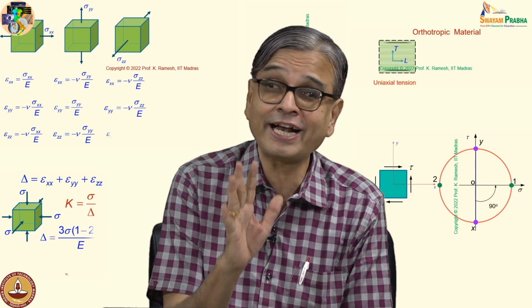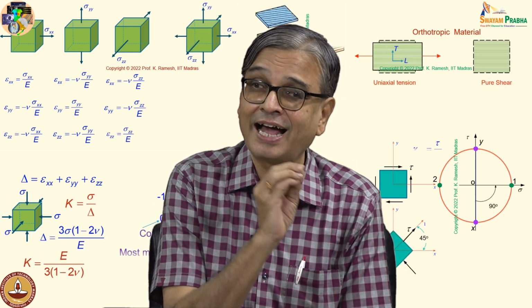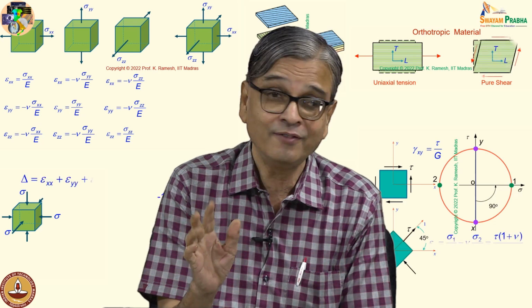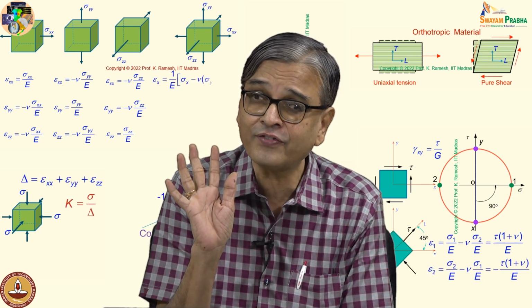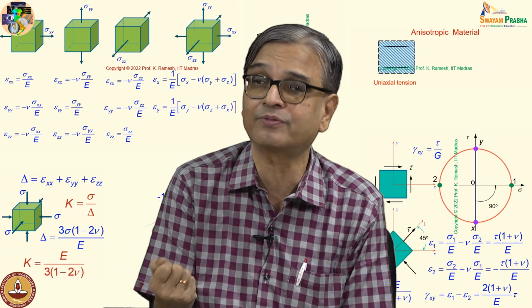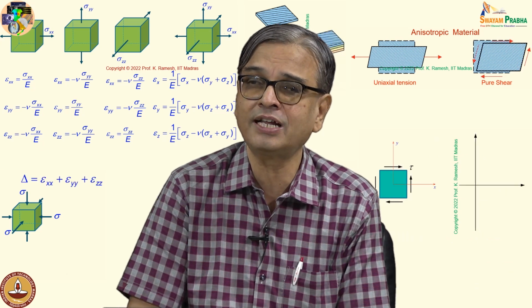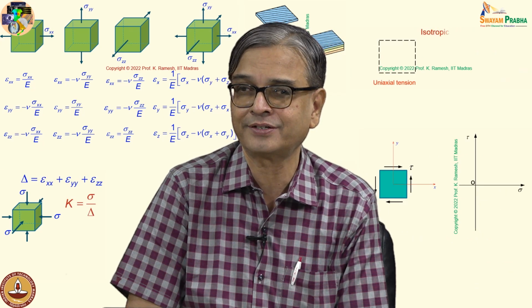Why do we want to idealize? Even though your extrusion process aligns the fibers in one manner, we still live in the comfort of isotropic material and handle it from an engineering point of view. You do a different test, use a different Young's modulus for you to handle the situation.